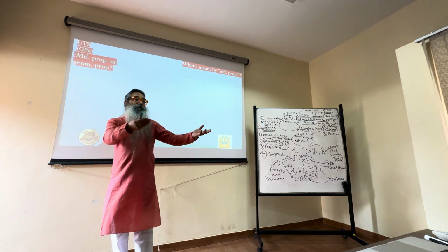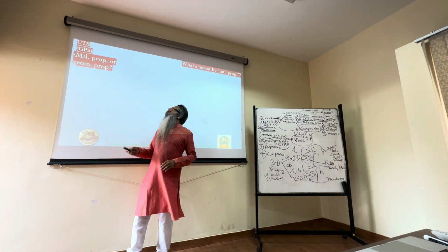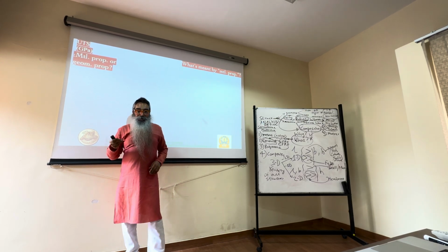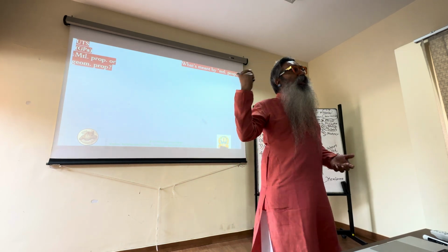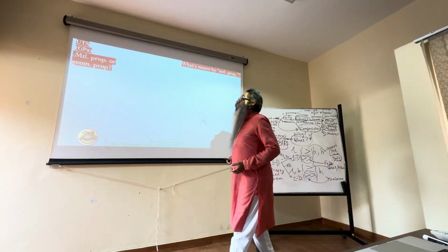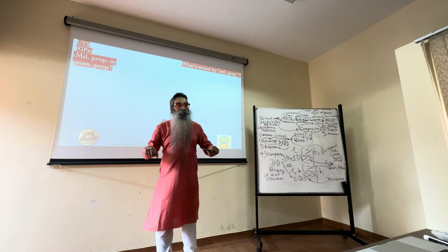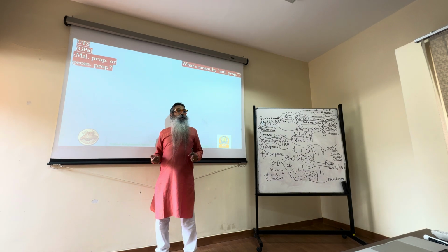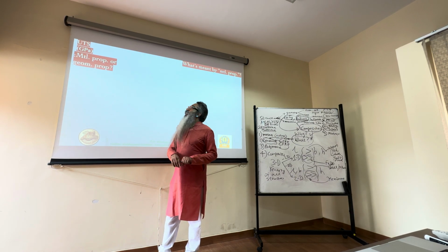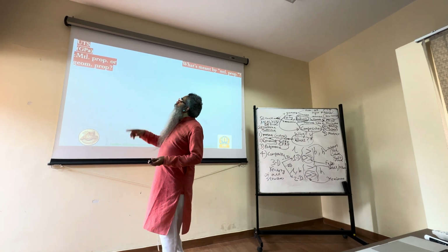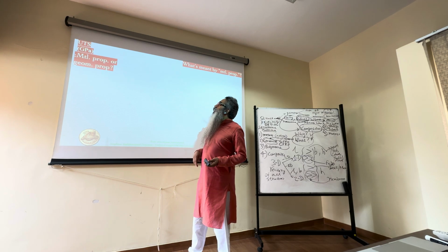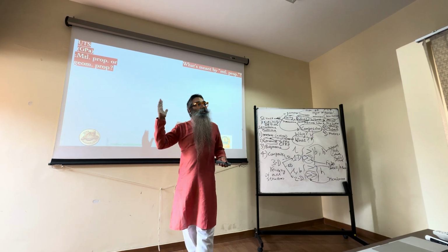So if that is the case, let's talk about this particular quantity. We gave density already as an example of a material property. Another material property that we have been studying is sigma u, which is called the uniaxial tensile strength, right? In other words, you're applying load only in one direction. You keep increasing that load to increase the stress, and at a particular value of that stress, the material fails, right? So that's the uniaxial tensile strength. Now, is that a material property or a geometric property?